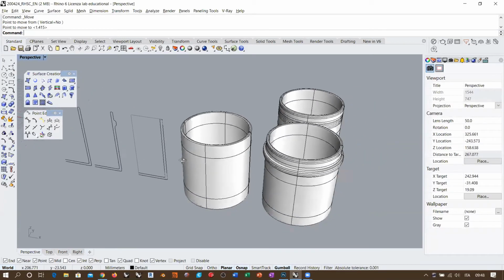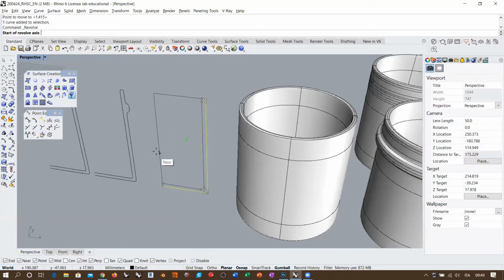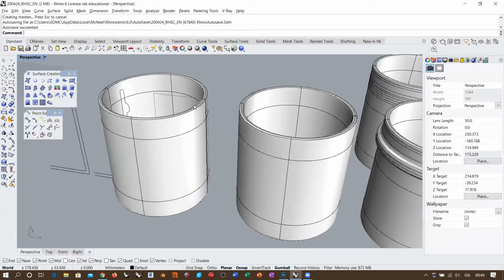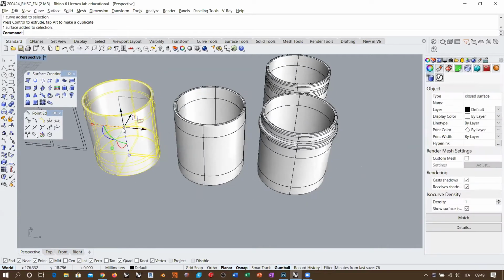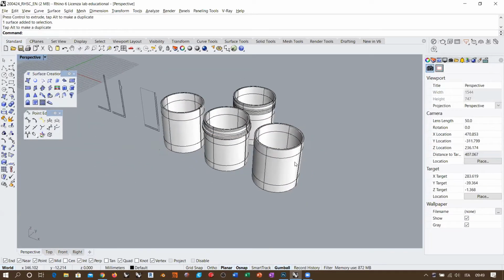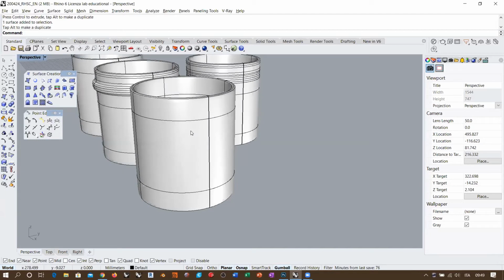So what we can do in this case is, okay, let's execute the revolve surface with the original profile without any topological editing, but with the right structure in order to create this smooth rounding here at the top and at the bottom. Okay, so we get to this surface. Now we know also that we did this with the curves, but we are actually going to do this with the surfaces. Now, what we can do with this surface is basically get to a more suitable topological condition in order to create local deformation.